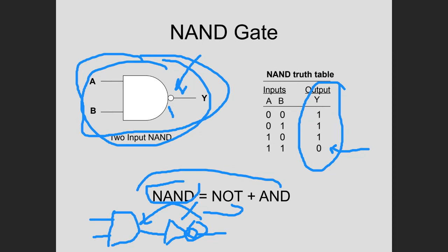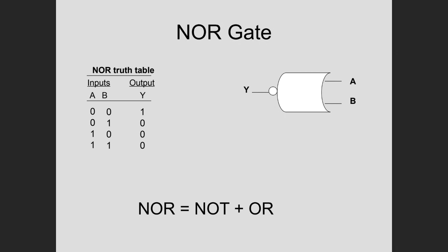And you can do the same thing with the OR gate. We can take a basic OR gate and connect an inverter. And again, I don't know why all my ORs and NORs are drawn the wrong way. Must have been something with the program I was using, because the ANDs seem okay, but these are all reversed. But anyway, we've done basically the same thing here. We added an inverter to an OR gate, and you guessed it, we get a NOR gate, a NOT OR gate.